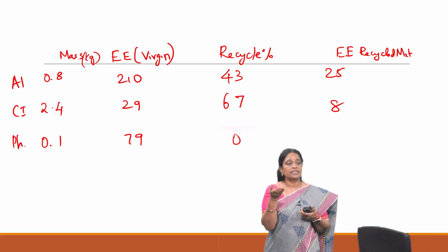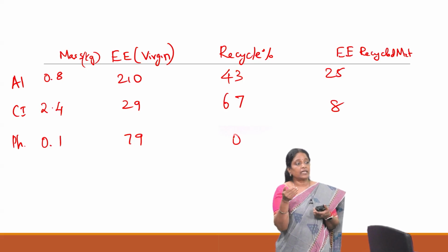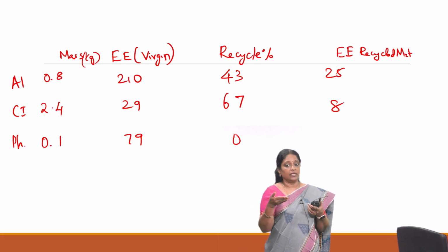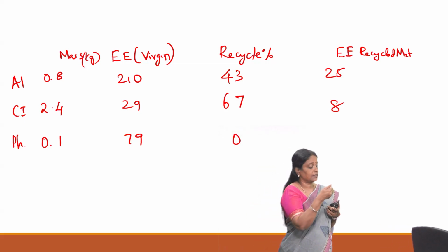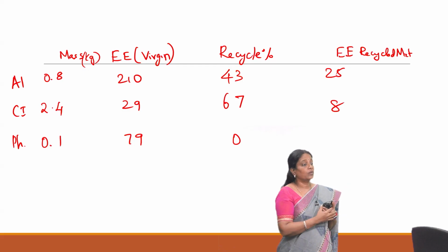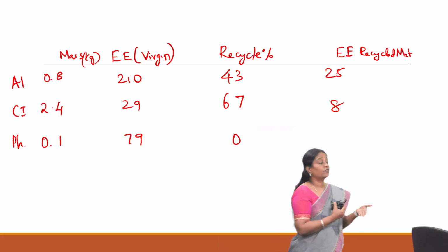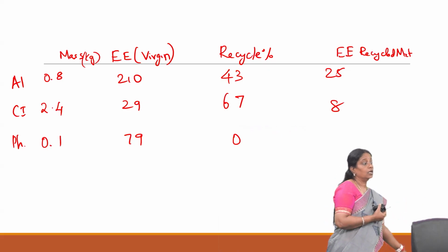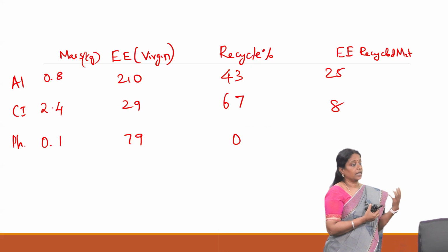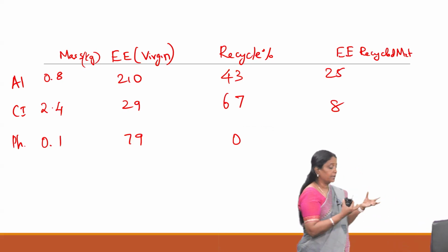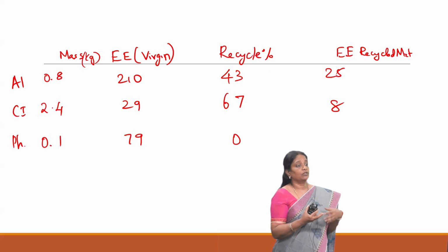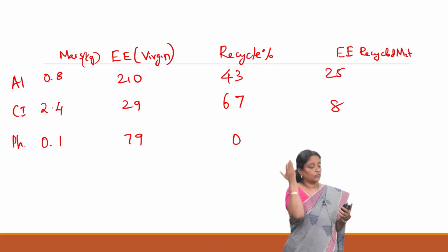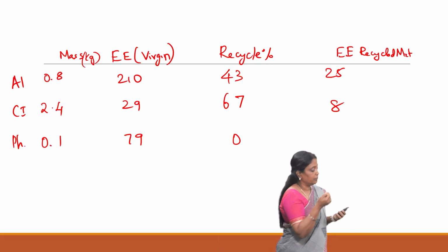You can see that even though recycling incurs a lot of processes and energy, it is not as much as the embodied energy of the virgin material. Even for metals, which are more energy intensive, you may have to melt the product, separate them, cast them again into molds and then send it for recycling. In spite of that, it is almost 1/10 for the aluminum alloy.